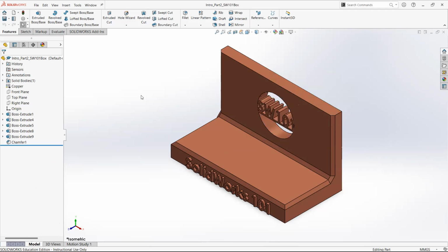And there is some distinction that you need to know: as you can see here, I can create 2 different rectangles. If I drag from the top left and go to the bottom right, I'll be creating a blue rectangular box, which simply chooses anything that is completely covered inside this box, as you can see this edge in here. However, if we go from the top right and we go down to the bottom left, we'll be creating this green box, which selects anything that is touching the box, even if it is not fully covered.